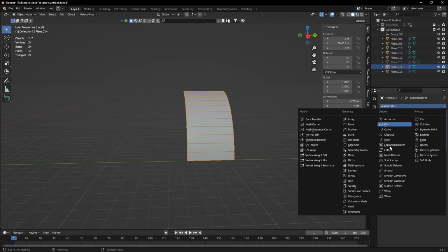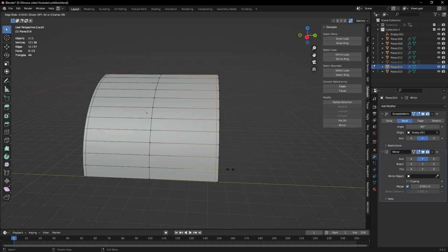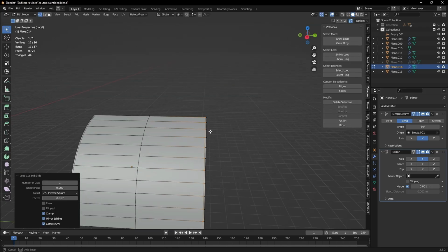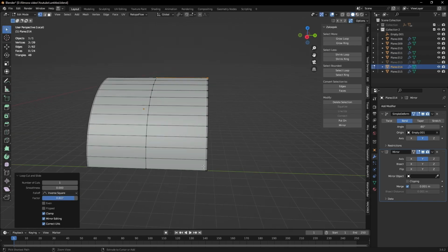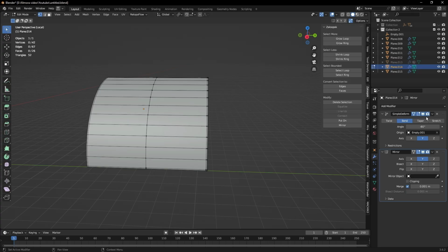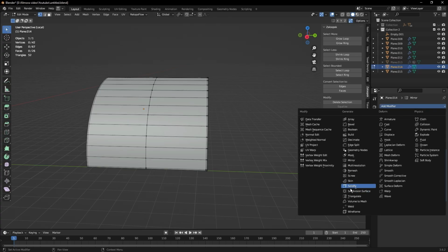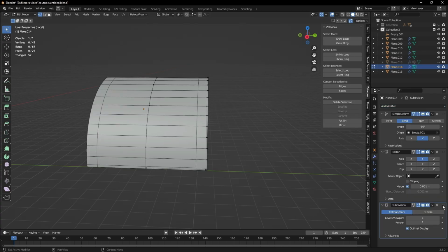Subdivision path. Sub-D needs careful support. At the inset border, add at least one, ideally two, vertical support loops, or the face will warp when you extrude. Add horizontal loops as needed. Fast trick. Create one center loop, then Ctrl-B to split it into two equidistant edges.